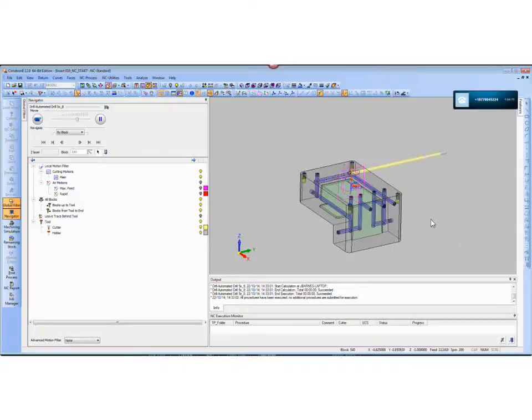And that's another thing I didn't mention was cost. Yes, these drills are expensive. They're a lot more expensive than a high-speed steel drill, but you have to consider the cost of the hole, not the cost of the drill. How long does it take to drill these holes, and amortize the cost of that drill across all the holes? Don't get sticker shock and say, well, that drill's too expensive, we're going to order the cheap high-speed steel ones. I understand that there's always limitations with resources, but please consider the cost of the hole, not the cost of the drill.